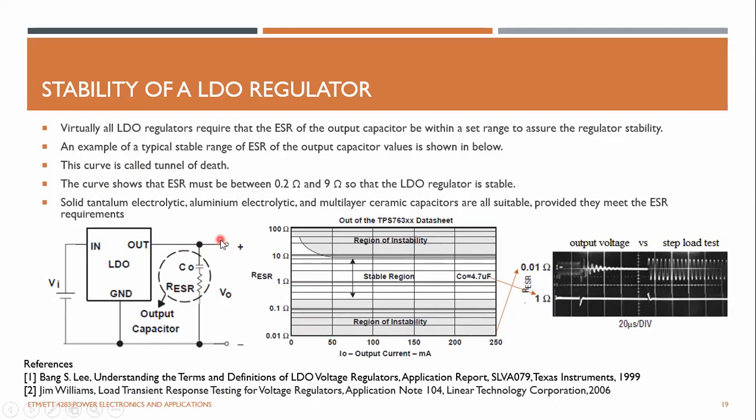So what will happen with an unstable supply if you don't make this regulator stable by using this capacitor? First, I will explain the concept. You need to have this output capacitor's equivalent series resistance within the desired level in order to make your regulator stable. That is basically the control theory part. We are not covering that one. It changes the poles and the zeros of the control loop in the open loop transfer function, which adds more phase margin. That is out of scope.